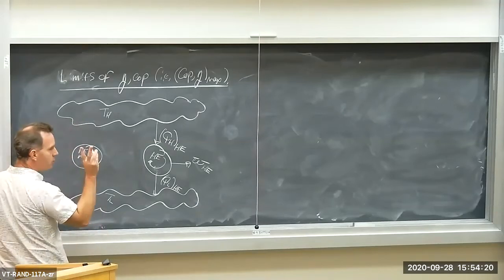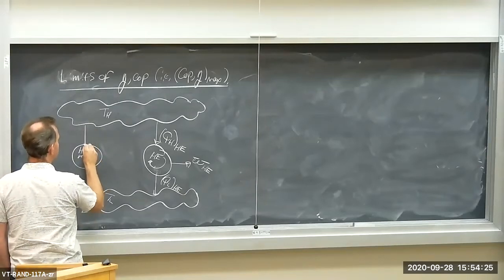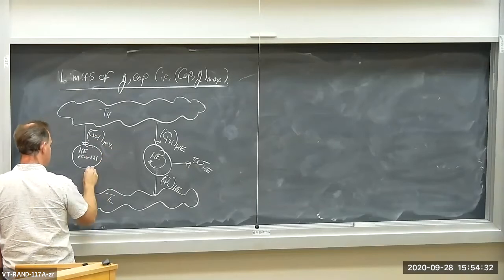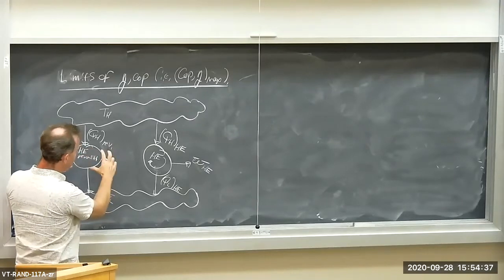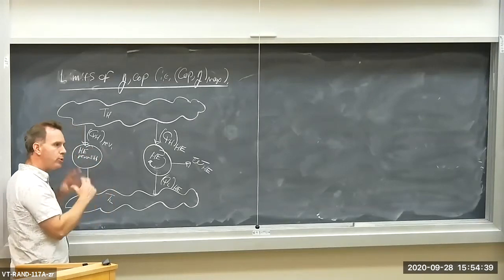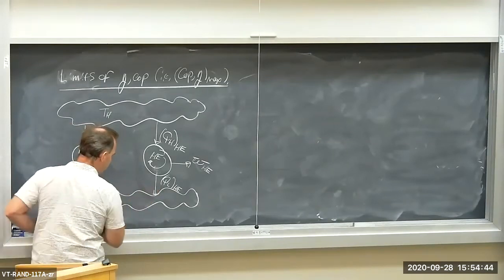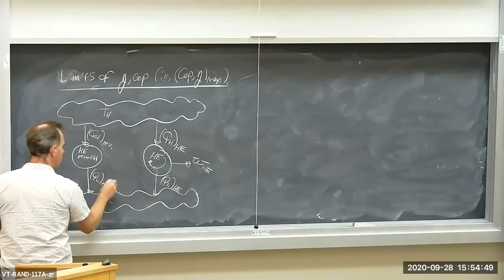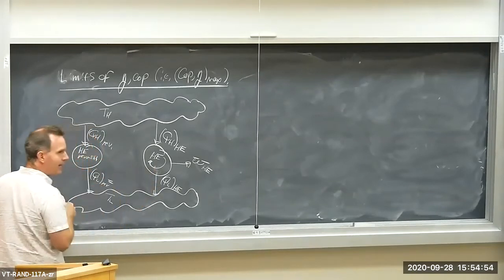So this reversible heat engine takes a certain amount of heat, QH reversible, rejects, and by the way, I'm going to make this reversible heat engine bigger or smaller in size, so that the amount of heat rejected by the reversible heat engine is numerically equivalent to what's being rejected by our regular heat engine.